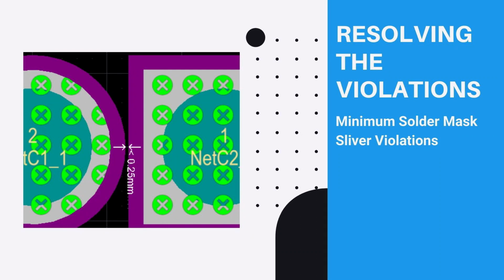During fabrication, solder mask is applied using different techniques. The lower cost approach is to silk screen it into the board surface through a mask. To allow for layer alignment issues, the mask openings are typically larger than the pads, reflected by 4 mil or 0.1 mm, which is the expansion value used in the default design rule.